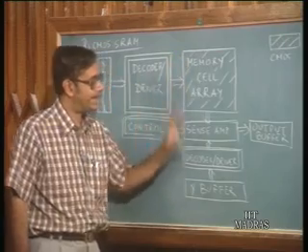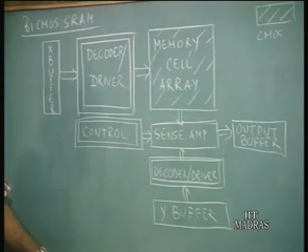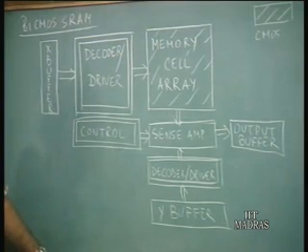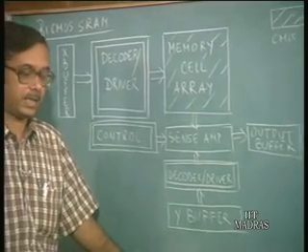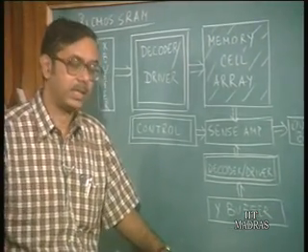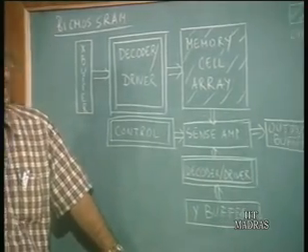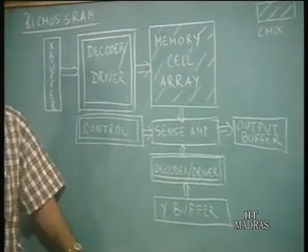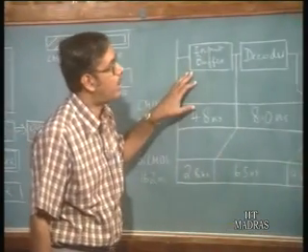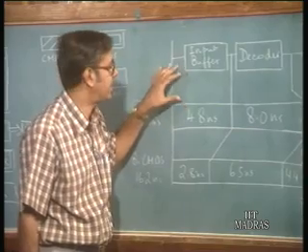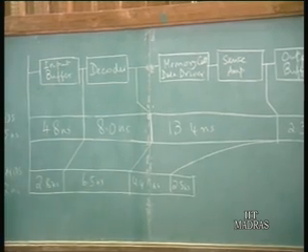So, with this type of modification, the CMOS memory can be converted to a BiCMOS memory, and this gives rise to a lot of improvements in power, and especially in the speed, or the reduction in the access time of the memory, that is, the delays are very much reduced. Here we show a comparison of the delays of a CMOS and BiCMOS memory. I will also give the reference.